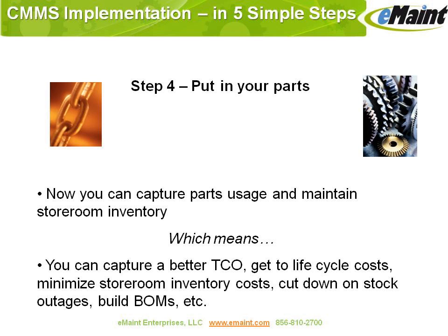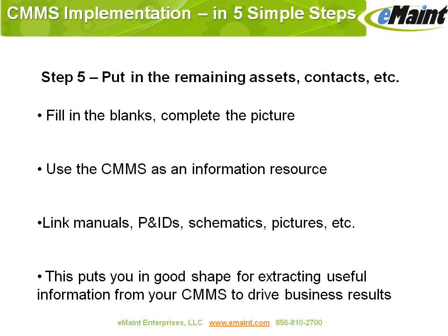Now, putting in your parts is a process that's probably going to continue over the life of the CMMS. The lion's share of it can be done at the beginning, but you can also approach this by just putting in the parts as you go. As you use the part, add it to the system, identify any suppliers, and also identify the equipment on which it goes. This takes a little extra effort at the beginning. It takes a little more time as you're doing it, but it also allows you to begin immediately and start building that parts list over time.